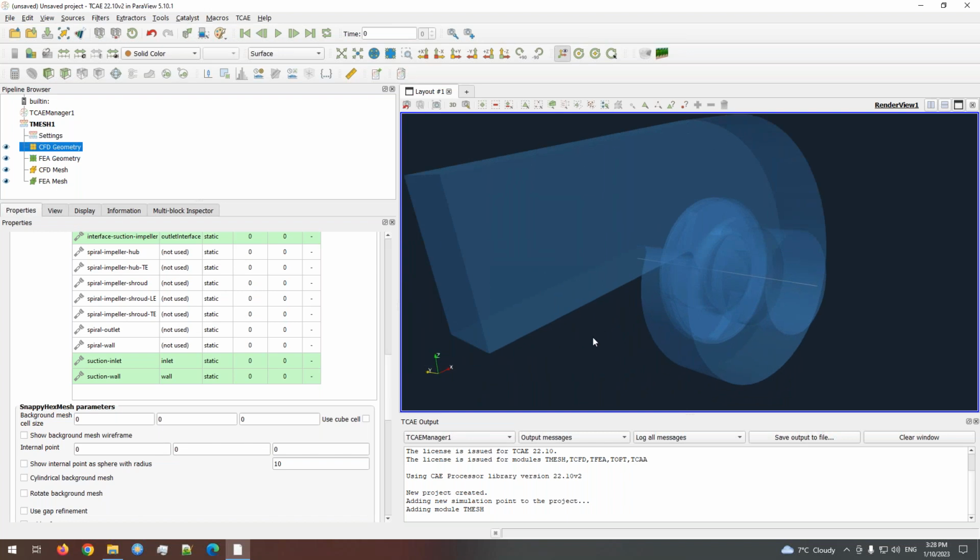Because now we are in the webinar, I will try to create some standard parameter variation for the mesh, which gives us a rough mesh, but which can be applicable for the CFD simulation, because I would like to run it live. So I would need a reasonable amount of cells to get the results quicker.